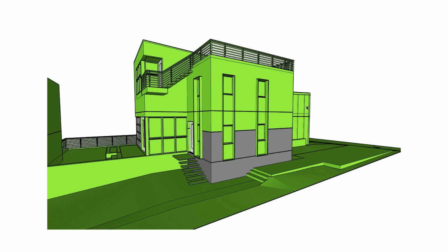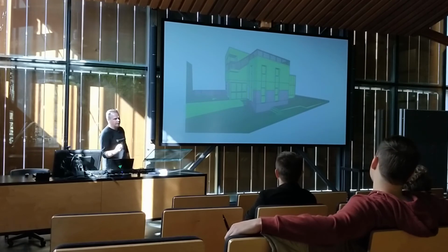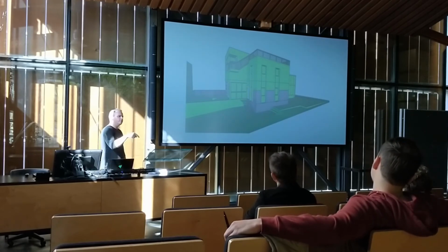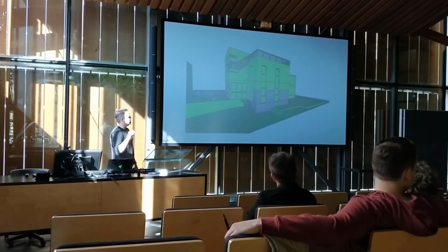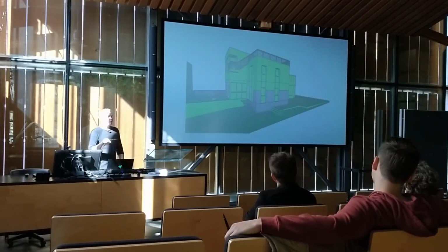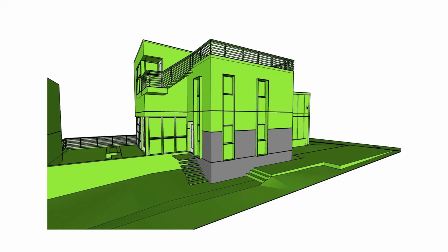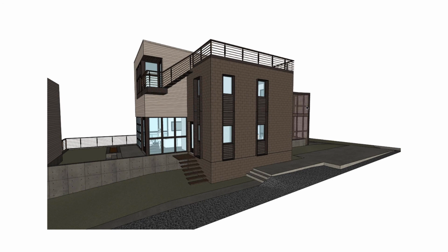All right, so then what this looks like, this is what we call a scope diagram. And this is in SketchUp, where we have a style that shows color by layer. And so our new layer is green, our existing layer is gray, and our demolished layer is orange. And this is a super informative way to look at a 3D model and just see that this is new, this is demolished, and this is existing. And so ultimately, that's what the model looks like.